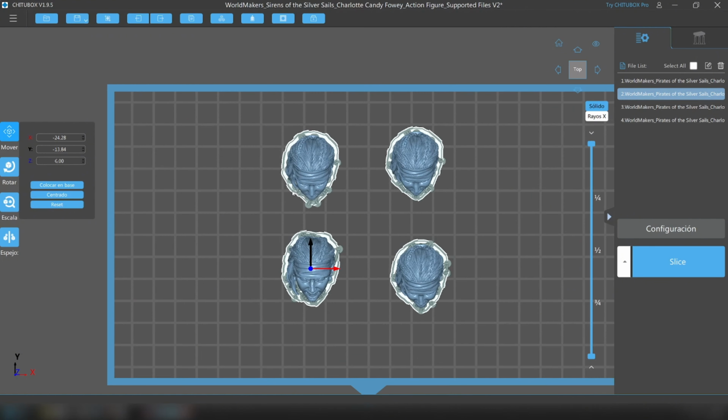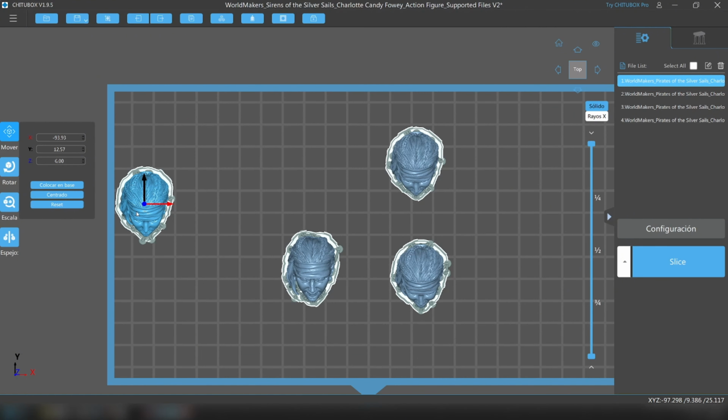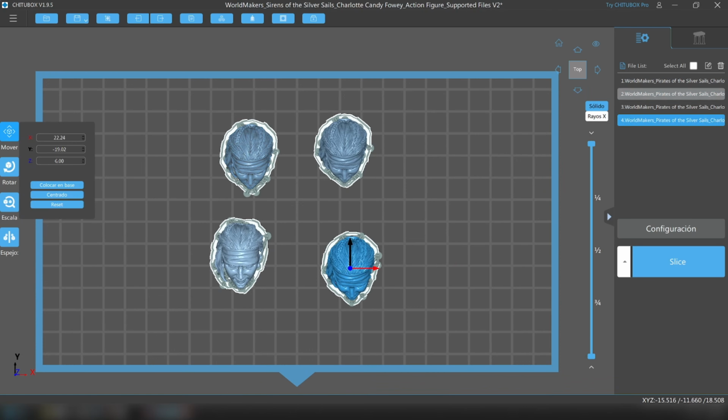And when you're printing, you see these lines here. Try not to touch them. Although you can print, this is very, very on the edge of the printer, and it can lead to issues with the FEP and all that stuff. So always try to keep it inside the boundary of the platform. So let's just go and slice.